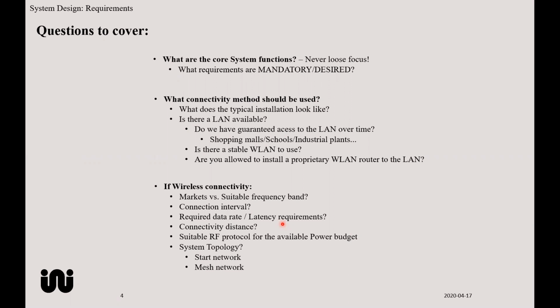If you are working on, say, 100 meters operating range between a gateway and a sensor node, most technologies like Bluetooth and Wi-Fi are questioned, but BLE long range or coded PHY might be very suitable for you. On the other hand, the peak data rate is reduced significantly, so that needs to be taken into consideration.